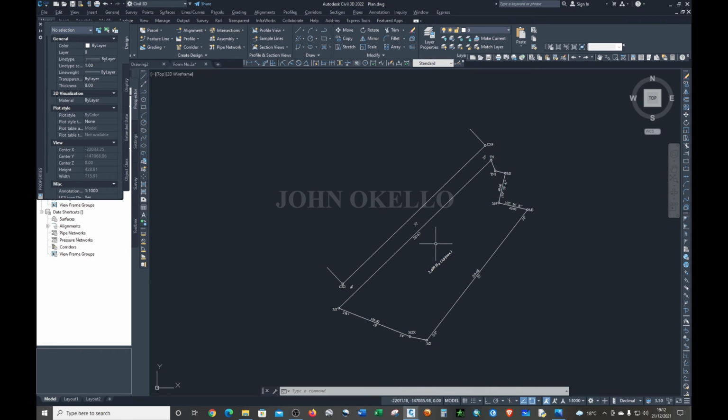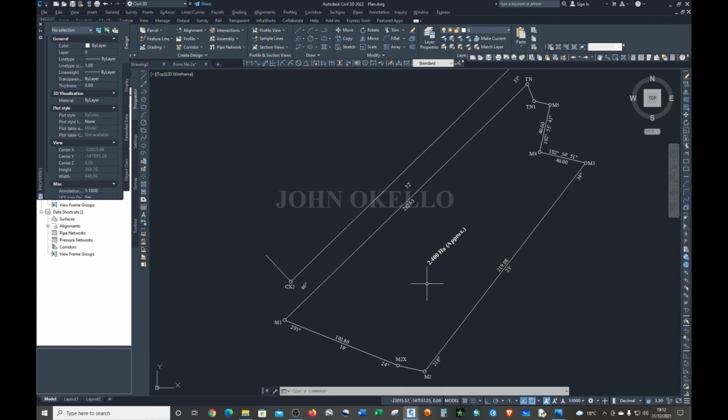Since this is in 1 to 1000 scale, if you divide 1000 by 10, that's the trick. You choose the denominator value, that's 1000, then you divide by 10, so you remain with 100. So that's 100. So the spacing in our grids will be 100.